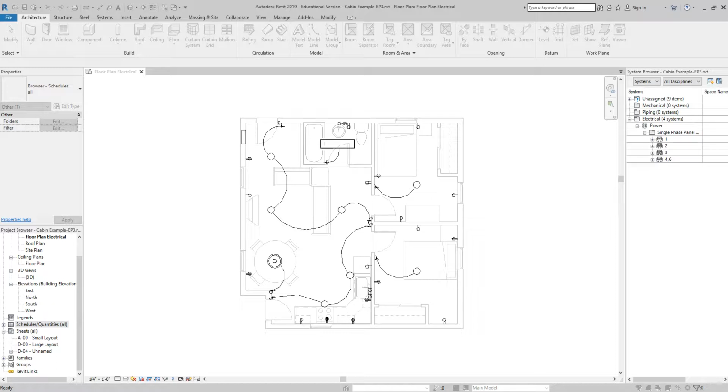It's now going to let me build the fields that are in my schedule. For those who aren't sure, a schedule is simply a table. So these are the columns of the different information, some of which will be pulled automatically, and one column we'll fill out on our own. The first thing we're going to use is circuit number. And you highlight it, and you click this box to put it in the field, and as it says, you want it in order.